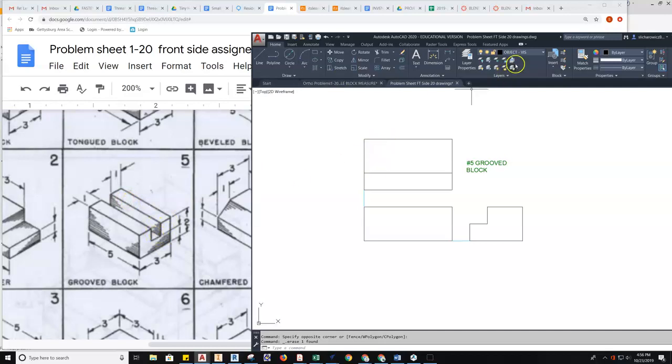down in the view. So to create an accurate view drawing, I'm going to sit on the end point, mouse up slowly, type in 1 to move the starting point of my line, draw across the part, click, hit escape, and now I've represented the top view of number 5 correctly. This is a top surface, second top surface, and then this is the groove down below.